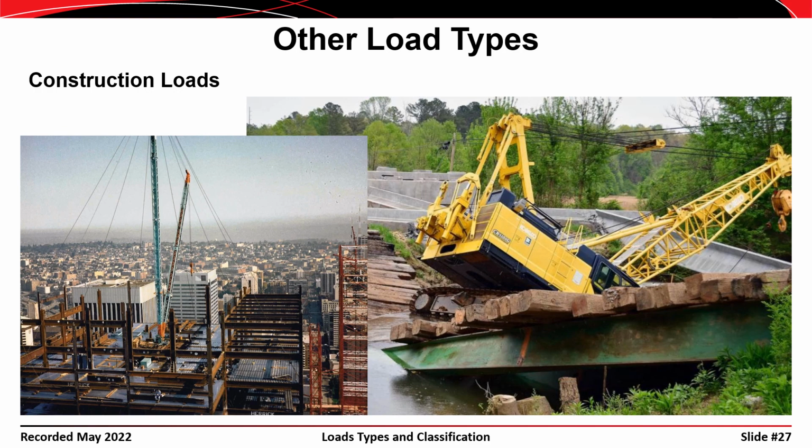Another case would be in the erection of steel buildings. Nowadays, it seems like most contractors use tower cranes, but in times past, or in at least some cases nowadays, they use derricks that are actually supported by the structure itself. So you might see loads in a structure due to derricks like this during construction that might be higher than any load that the structure would see during the service life.